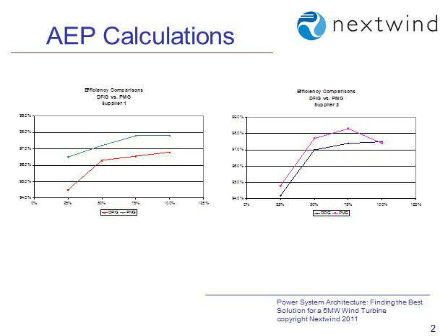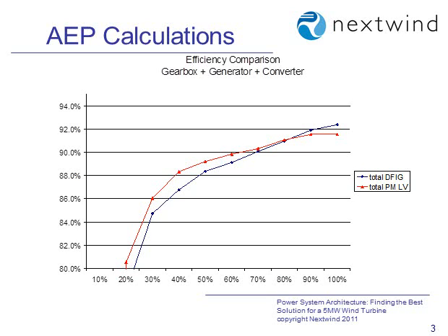But looking at the generator by itself isn't really telling the whole story, so you have to add the efficiency curves of the generator, the converter, the gearbox, and also the performance curves of the blades. To do that, you come up with this nice curve, and this is the really interesting one in my opinion.